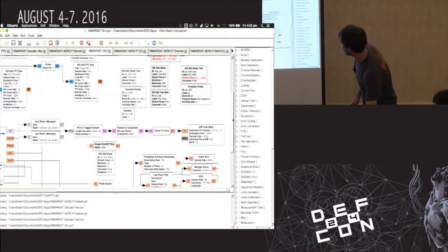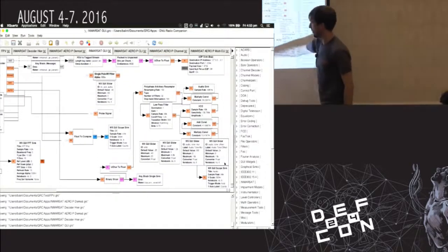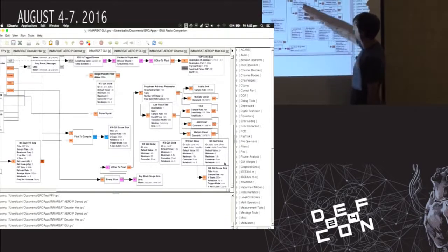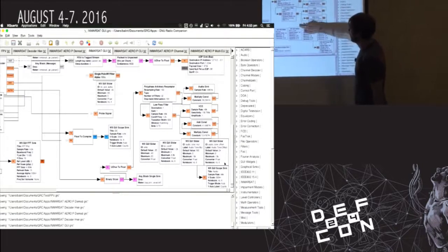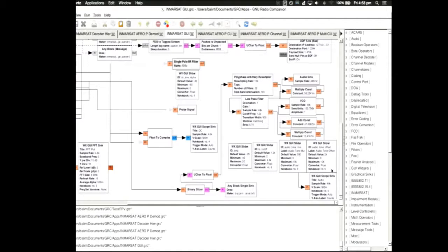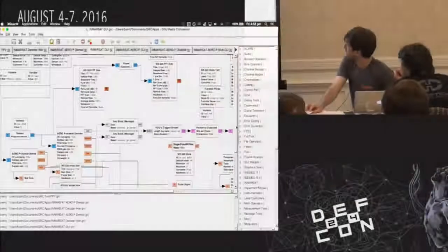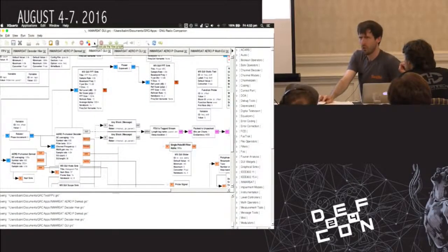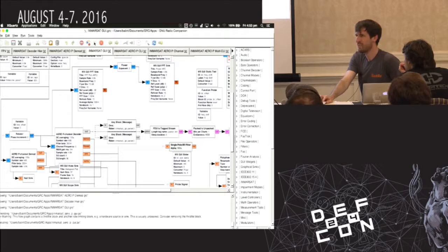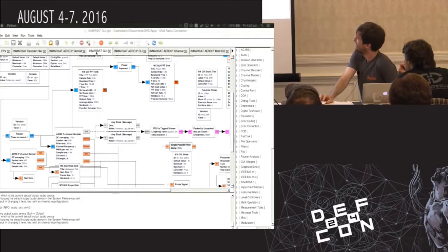And then in this corner is the audio output. So basically you're taking in your bits here, you're resampling them to an audio rate, doing some filtering, using a VCO to generate one of 2 tones, moving those tones and the separation between them, and then going out to your audio sink. So that's just a nice little visualization. Audio. What's the term to convert it? Sonification, sonifying.